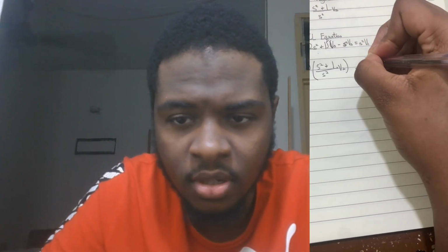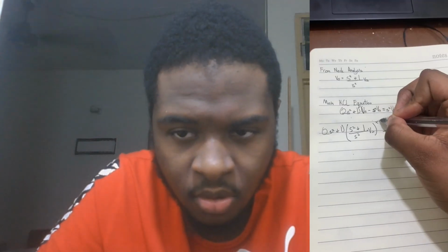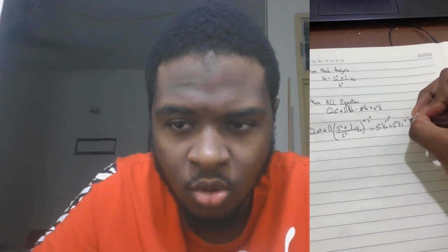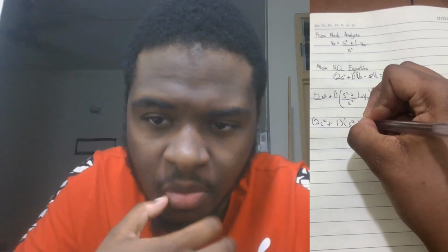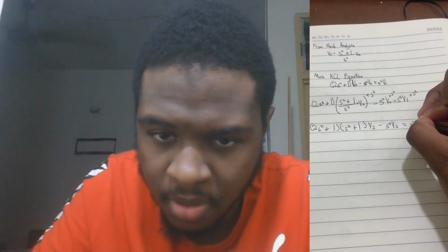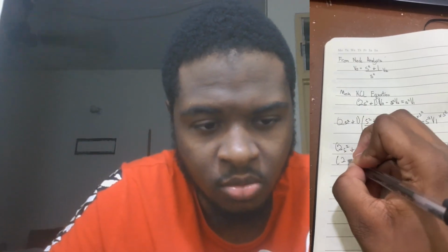My name is Daniel Dromo, and my role is to solve the equations and obtain the transfer function. From the previous step, we found that VA is equal to S squared plus 1 over S squared, all times V2. I'll substitute the expression directly into the main node equation. We have a fraction now, so to simplify it, I'll multiply every term on both sides by S squared so that the equation stays balanced.